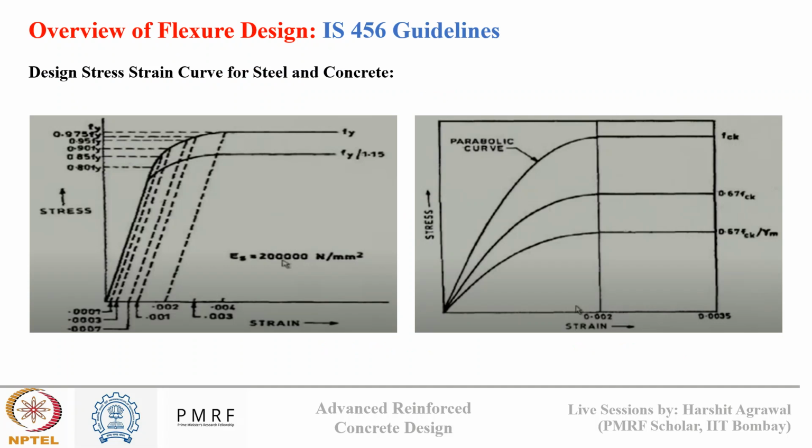And for concrete, we understood how different safety factors, like 0.8 for converting cube strength to cylinder strength, 0.85 for the size criteria to differentiate between the large scale concreting on field and small scale concreting that we do in laboratory, and 1.5 as an additional safety factor, all combine to bring the characteristic strength from fck to 0.45 fck.